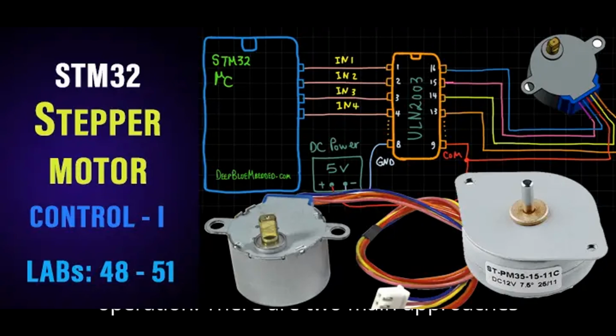There are two main approaches used to control the motor. AC voltage control. In AC applications, the motor driver controls the voltage applied to the motor by adjusting the power supply. It typically uses a triac-based phase control or thyristor to adjust the power waveform fed to the motor. This is often done through phase-cutting methods, such as zero-crossing switching. In this mode, the motor speed is proportional to the voltage applied, but control can be somewhat less efficient compared to DC control.